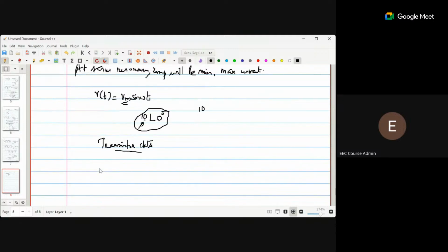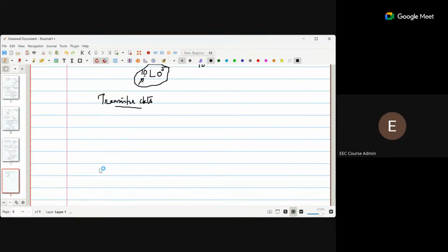So transistor, even through the quiz or in the week 7 discussion, we had seen the main thing is voltage divider biasing: R1, R2, RC, RE. Then if you consider the common emitter amplifier circuit, you have the coupling capacitors, then here the bypass capacitors. So you should know the role of these coupling capacitors and the bypass capacitors.